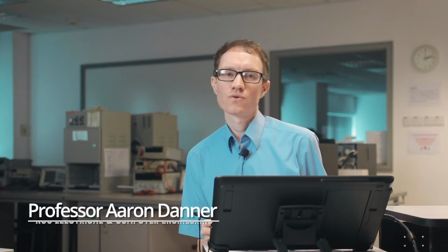All right, in this video, we'll discuss superposition. And superposition is a property of linear systems. This method can only be applied to circuits, say, that have a lot of voltage sources, resistors, and current sources. You can't apply superposition to a circuit that has nonlinear elements. And examples of nonlinear circuit elements are things like diodes or solar cells, or any circuit element really that has an IV plot that's not a straight line.